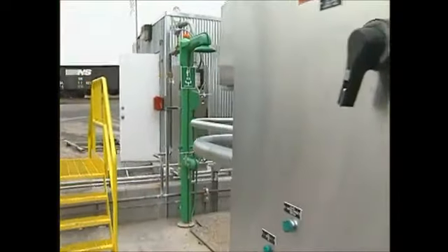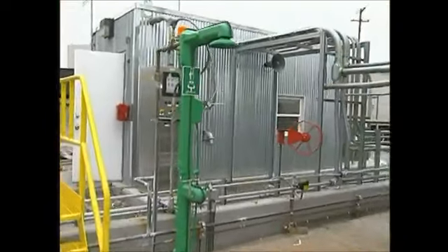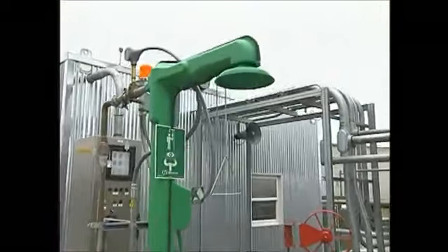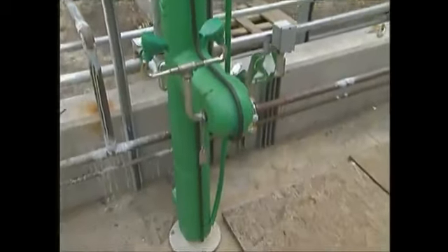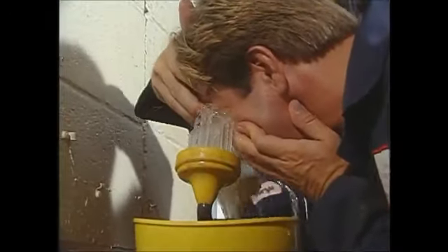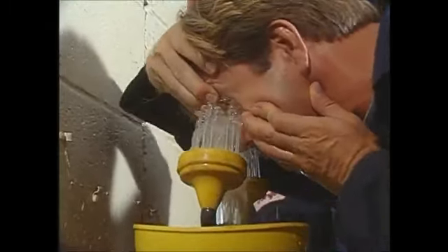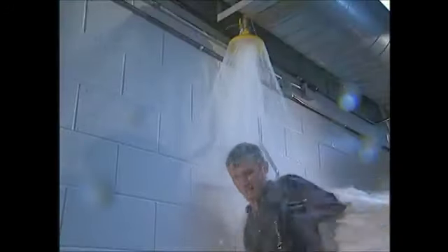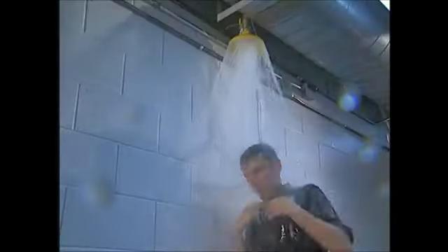Finally, when you're working with or near hazardous chemicals, always make sure you know the location of eye wash stations, safety showers, and the number for the Poison Control Center. If your eyes are splashed by chemicals, get to the eye wash fountain immediately. Hold your eyes open in the water and flush them continuously for 15 minutes. For larger splashes, get to the safety shower without delay. Step into the running water and remove contaminated clothing while in the shower.